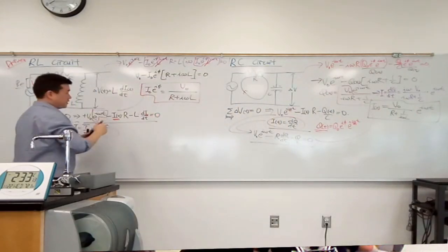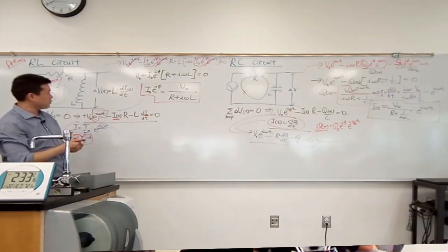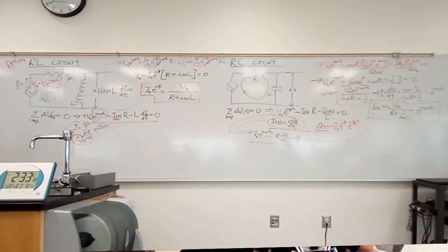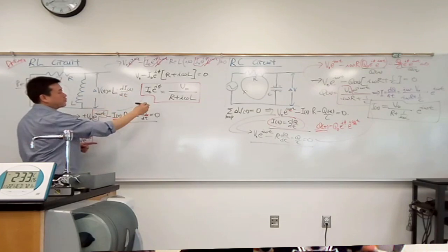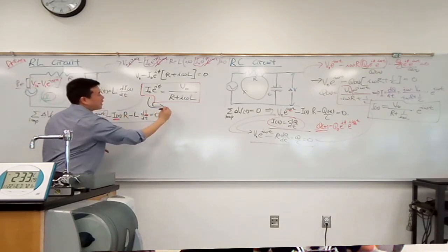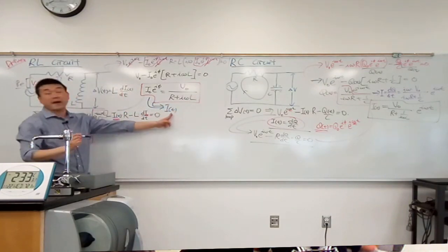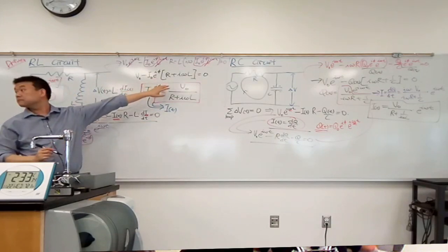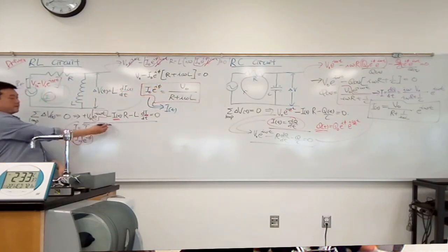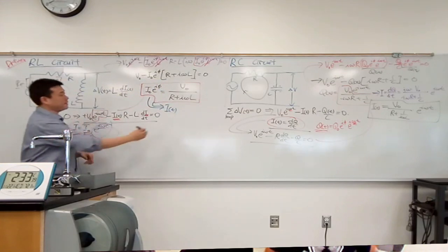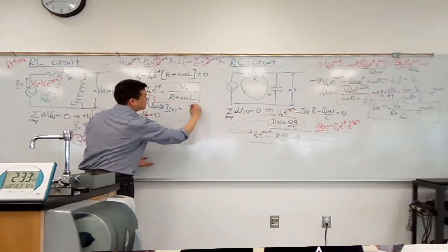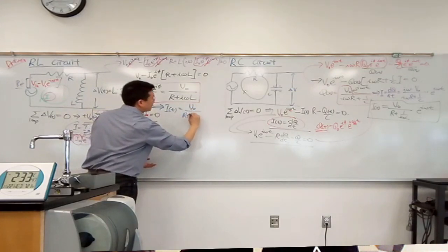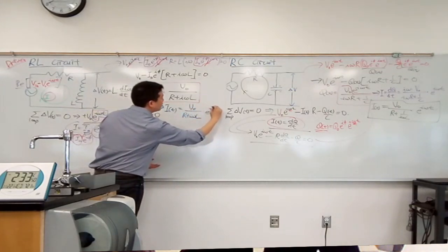When you look at here, I really should have done the same thing across. Sorry, I'm switching back and forth. My apologies for this confusion. If I want to describe current as a full function of time, then I should take this and multiply back this e to the i omega t. Let me write that down so that I can compare the same expression throughout. Current as a full function of time is V naught over R plus i omega L times e to the i omega t.